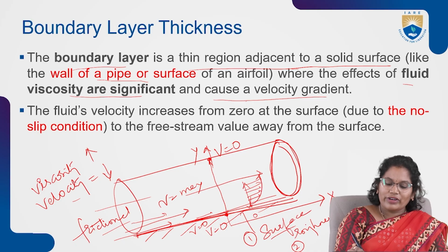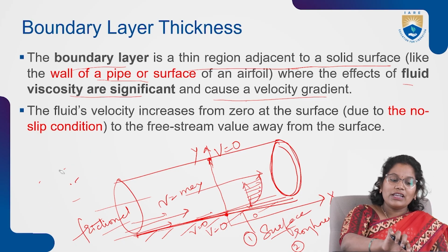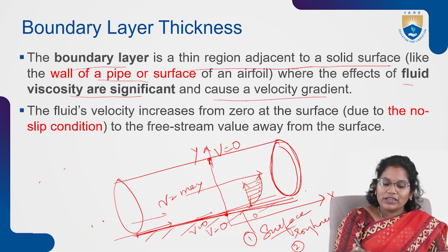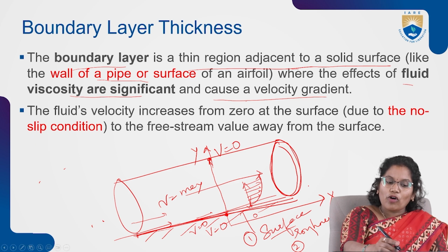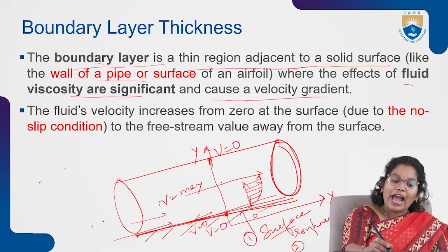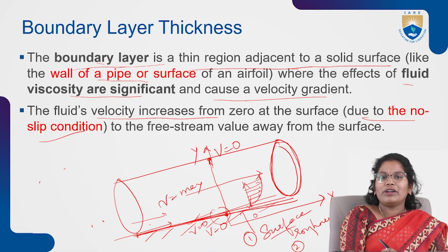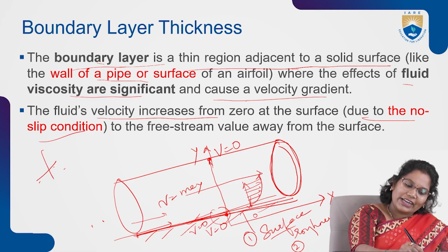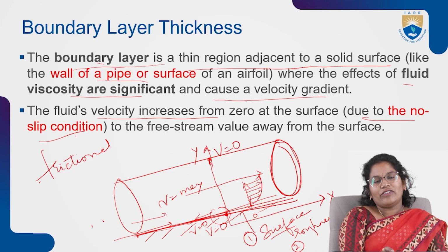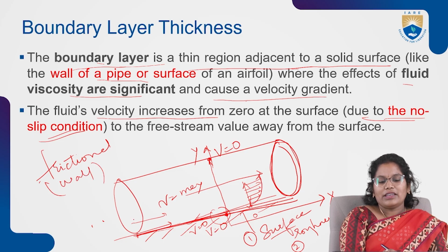So depending upon the viscosity of the fluid and the surface roughness, we are seeing frictional resistance which opposes the flow and forms a boundary layer, that is a thin layer occurring at the boundaries, right? Here the velocity is zero at the boundary because of the no slip condition. No slip condition means frictional resistance is active. The frictional resistance is acting at the wall, right?